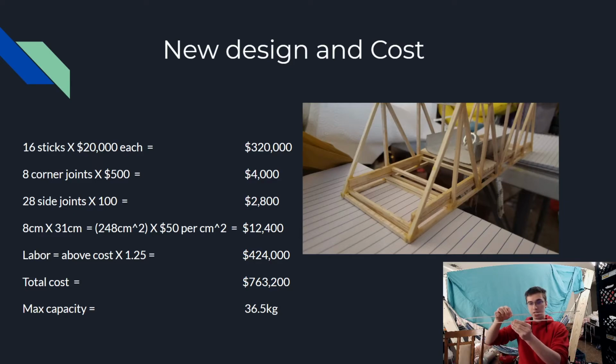The more that you can increase the height here, the stronger it becomes. So you want it to have more vertical height there. So that's what I did. I stacked 3 members on top of each other, and then I also put crossing members so that they didn't just buckle out from underneath the sides, so that they could actually use the strength of it.